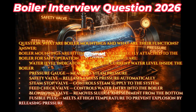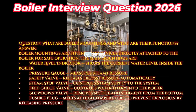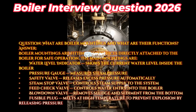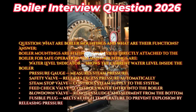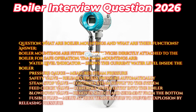Question: What are boiler mountings and what are their functions? Answer: Boiler mountings are fittings and devices directly attached to the boiler for safe operation. The main mountings are: a water level indicator, which shows the current water level inside the boiler. Pressure gauge measures steam pressure. Safety valve releases excess pressure automatically. The steam stop valve controls steam supply to the system. Feed check valve controls water entry into the boiler. Blowdown valve removes sludge and sediment from the bottom. Fusible plug melts at high temperature to prevent explosion by releasing pressure.